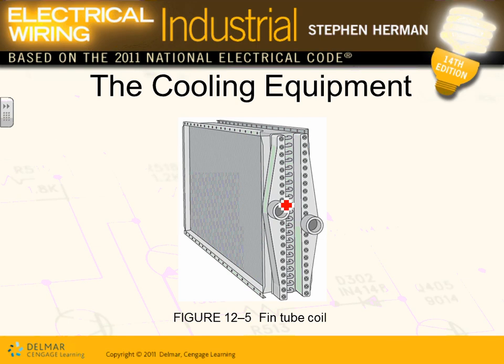Okay, so that's basically the equipment, guys. Cooling equipment, we talked about the refrigeration cycle. They compress the refrigerant, guys, in the chillers. You saw the chillers. They compress it and circulate it between the compressor, the evaporator, and the condenser. They pick up the heat from the building and exhaust the heat through the air handling unit outside. I'll get you one mechanical presentation about these as we move on. I have a nice presentation about how they interface.